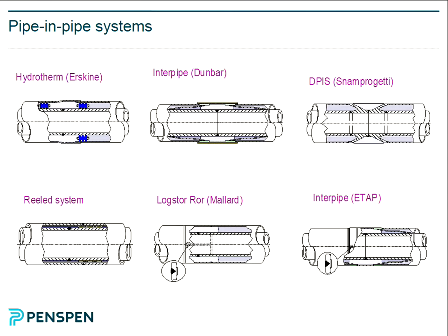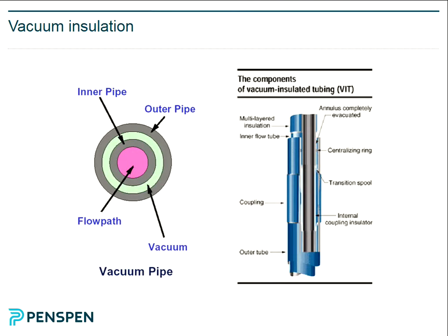Not going into this in detail, but the other thing you need to consider, of course, is stationary cooling, because under a steady state operation of a pipeline, you've got an inlet temperature, say for example that's 100 degrees. The outlet temperature may be 30 degrees under steady state, but the wax appearance temperature may be, for example, 25. So under normal operating conditions, that's fine.